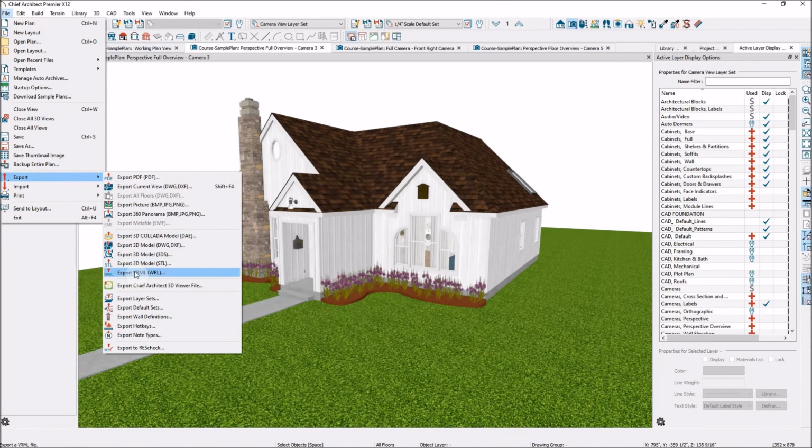And then you're going to choose from one of these 3D file formats. And typically I am going to either export as a Collada file or a 3ds file, depending. If I'm going into Lumion, I'm doing a Collada file. If I want to render into the eDesign Tribe platform, then I have to process this through SketchUp. You can only upload a SketchUp file. You can't upload any of these files into eDesign Tribe. So you have to process it through SketchUp first.